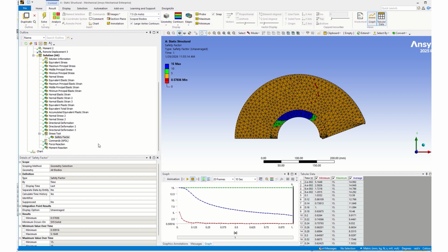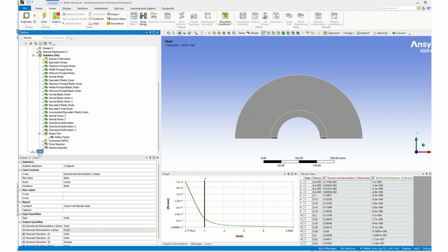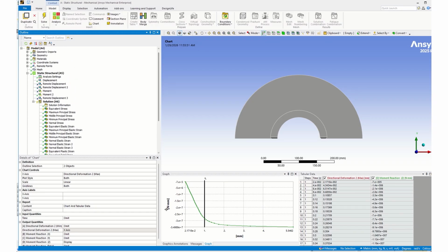The telltale result is to come down here and plot the load deflection curve and see that we cannot apply any more moment without just gathering extremely large displacements. So this was based on this load condition. We got a maximum moment of 3.5e7.